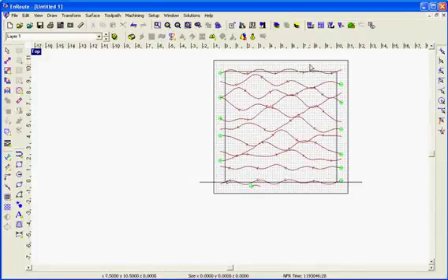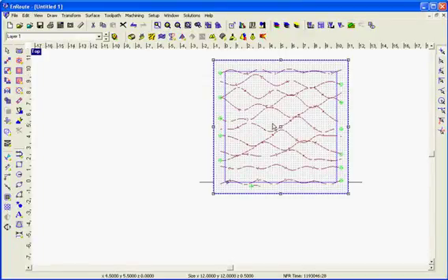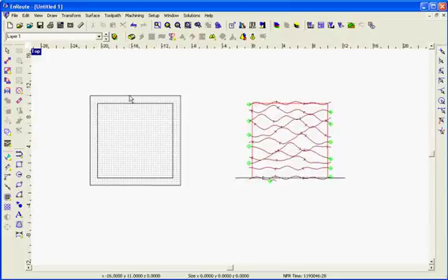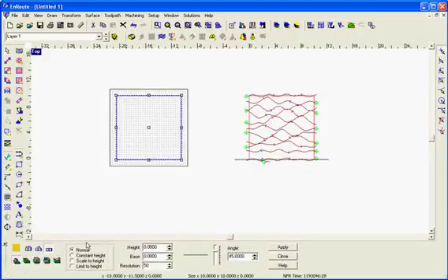First I'll delete the contour I used to create the simulation. Then I'll select my material size and the relief and slide them over here to the side. Now I'm going to trim away the boundary of the unnecessary part of this, and I'll do this by just going here and creating a flat, no thickness relief within this inner part.